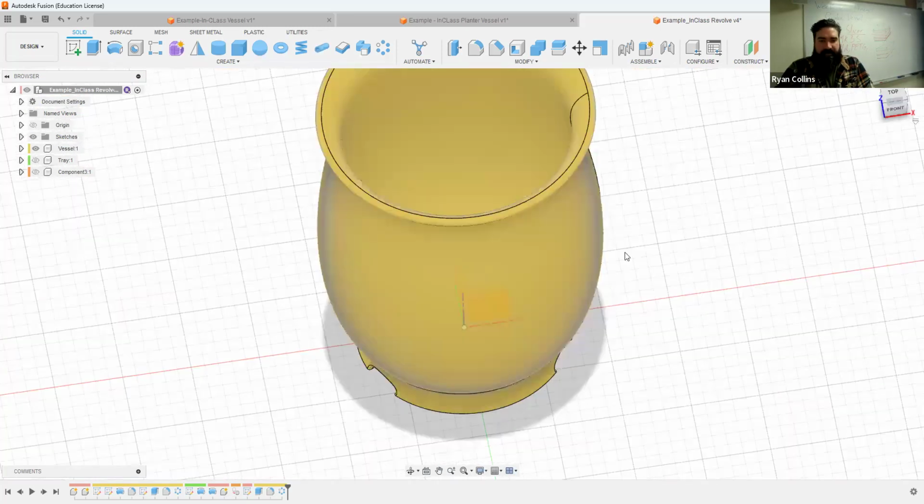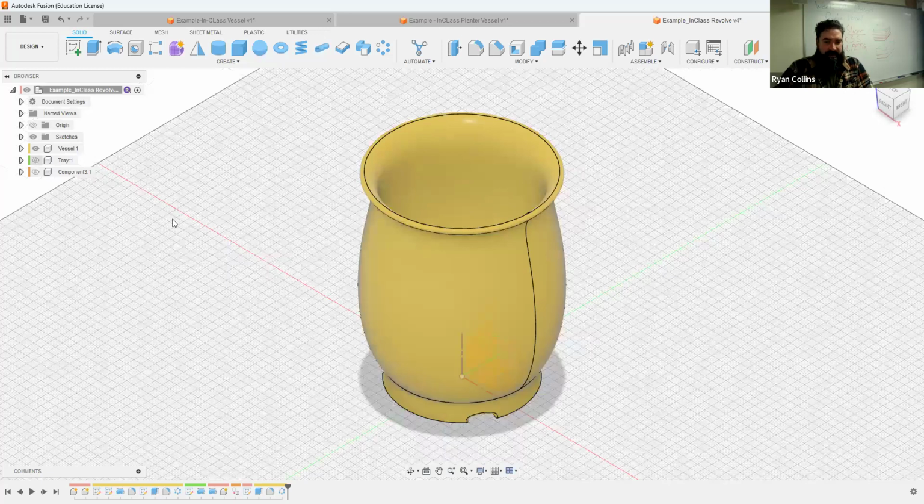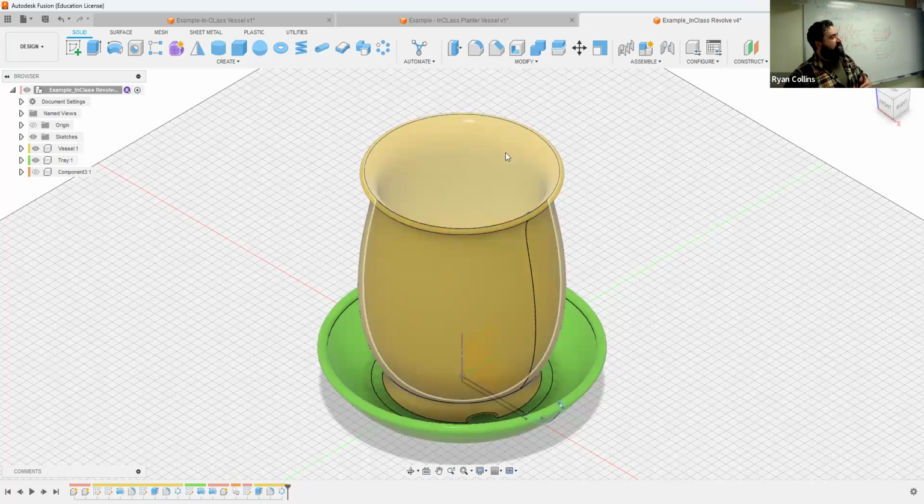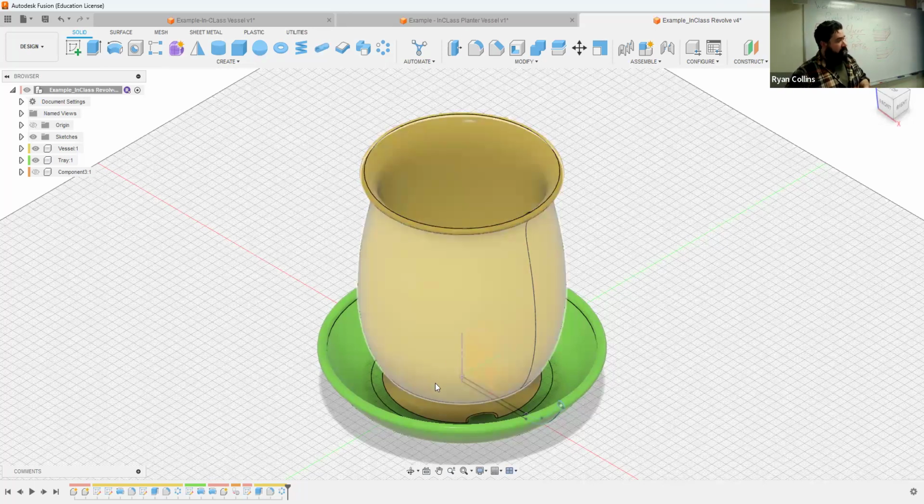All right. The other thing I wanted to show y'all is a more advanced option. If you are feeling a little more ambitious or you have some experience, you're going to be using either the cut, meaning the extrude and cut, or the emboss tool. Now, to make this more effective, it is easier to make a sketch floating outside of your project. Basically, what I just did with that extrude starting offset, it's a lot easier to not have it right in the center of your project.